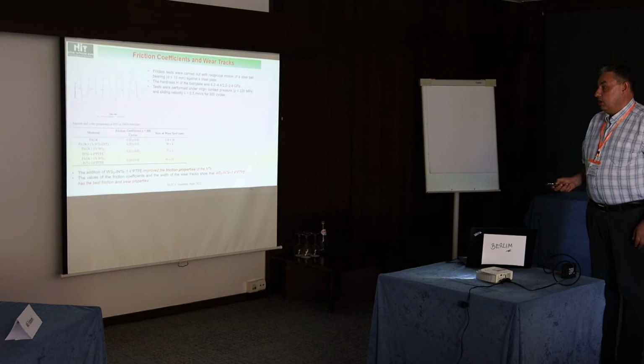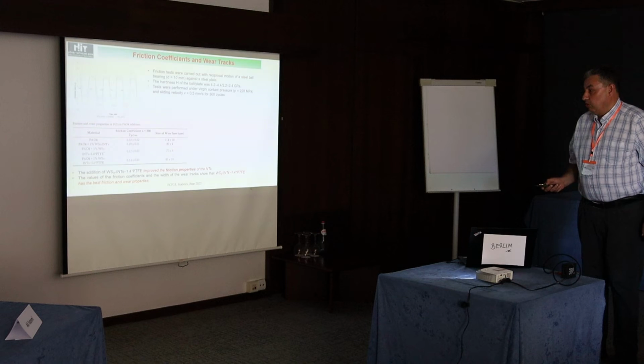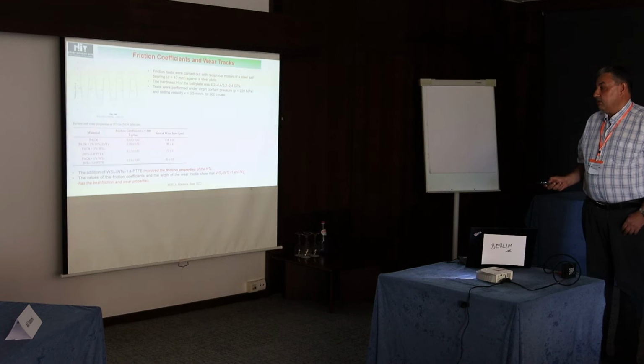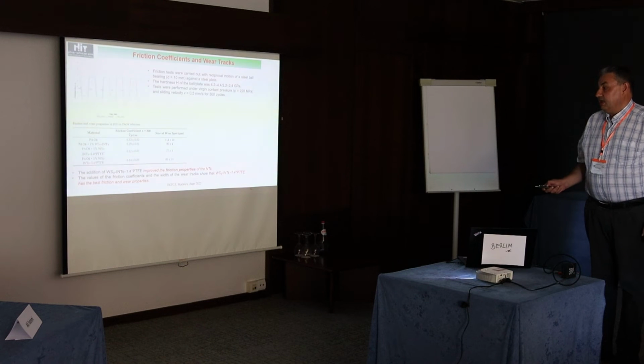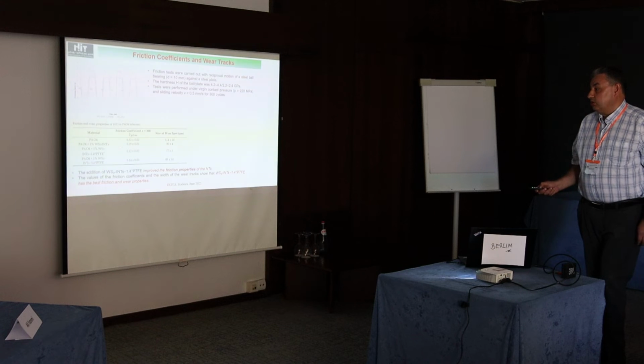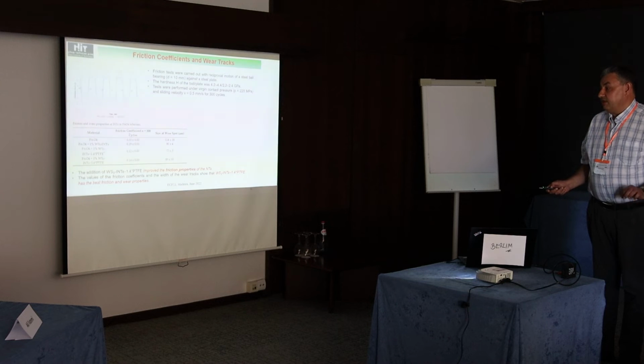The tests were performed in PAO4 oil, polyalpha-olefin oil. So these are friction coefficient for the oil itself, and also the size of the wear spots. And as soon as we introduce nanotubes, we already see a decrease in both friction coefficient and wear spot. And for this type of relatively low Teflon concentration, we have the best conditions. So the friction coefficient is 0.12 and wear spot is 77.